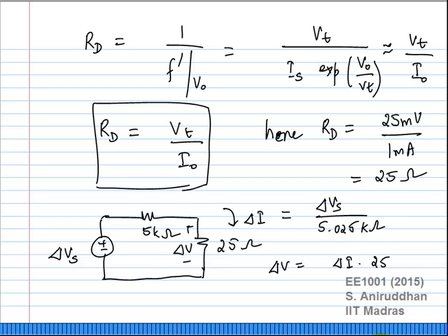But the minute you establish the operating point, for any other small change in the applied source voltages or currents, you can draw the incremental equivalent circuit and figure out what will happen to the increments across any element in the circuit using just a linear system of equations.